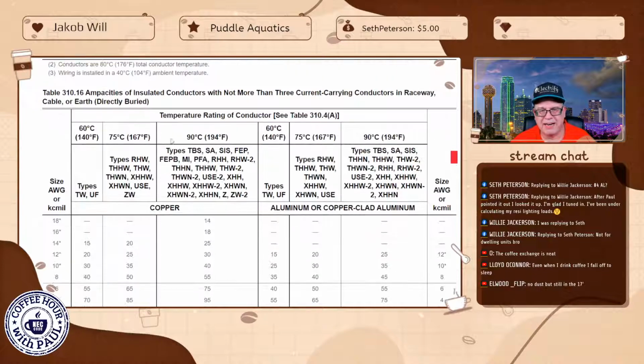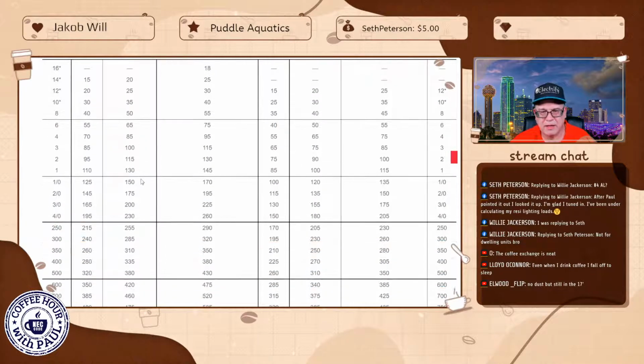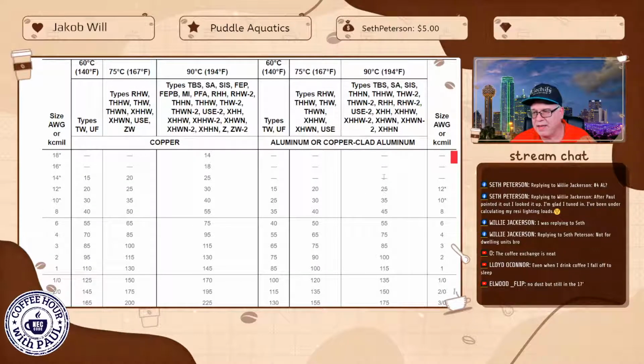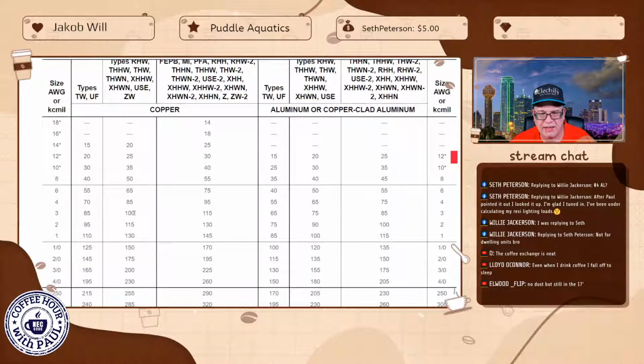Okay. So here we are right here under 75 degrees C. So 136. Let's see here. We're under our sizing here. Remember, we were doing the 83% rule. So that's how we got that value. But we were doing the neutral this time, and that was 89. So 89, that's where we got the 3 right here. Just made it and just jumped us into the 3. So 3 is good for 100, and our neutral was 89. So that's why that's a 3. But if we were choosing over here, we got to jump into a 2. And that's what we've got for the 100, good for 100.